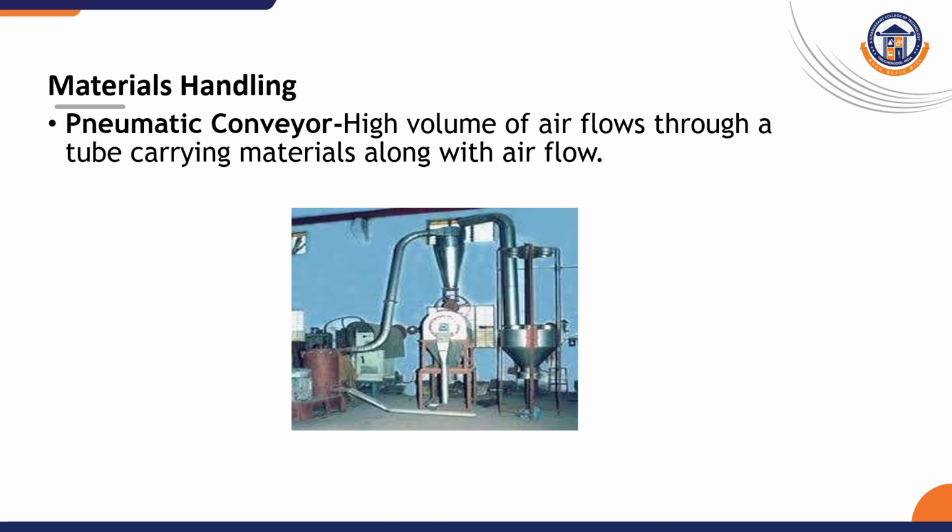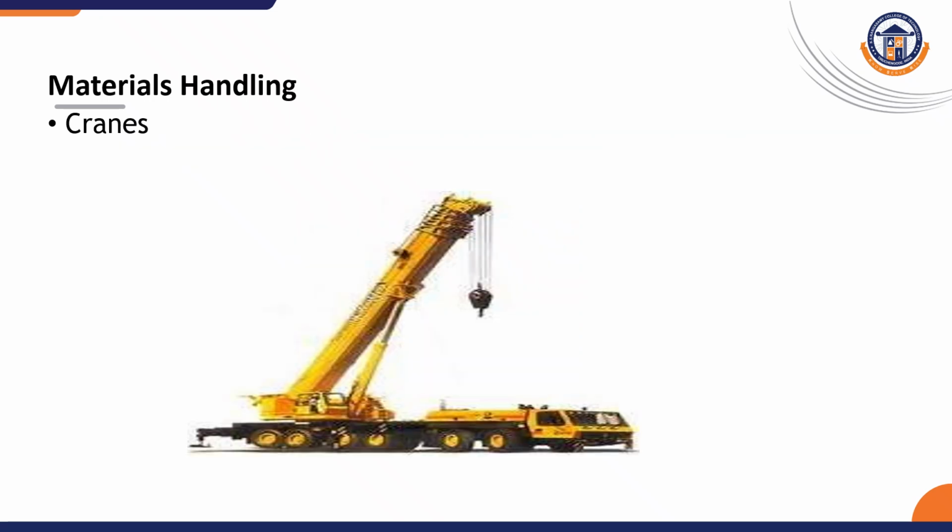You are seeing a non-textile product. This happens in textile chemical processing, but in yarn manufacturing there is a place called the blow room, which is the costliest machine in the manufacturing process. It is around 50 feet long. A lot of material has to be put in. It actually sucks the air through the tube which you see in this photograph. It sucks the cotton or polyester fiber and conveys it to the other machine. Continuously, it takes that. So it is called a pneumatic conveyor.